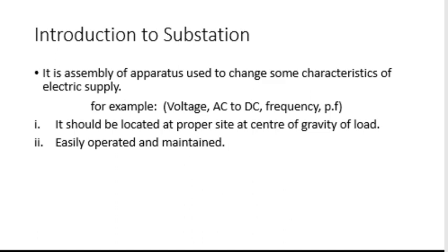It is not like the generating substation, which you have studied should be far from the load centers. But when we are talking about the consumer substation or the lowest substation, it should be at the center of gravity of load, so that it can be easily operated and maintained.